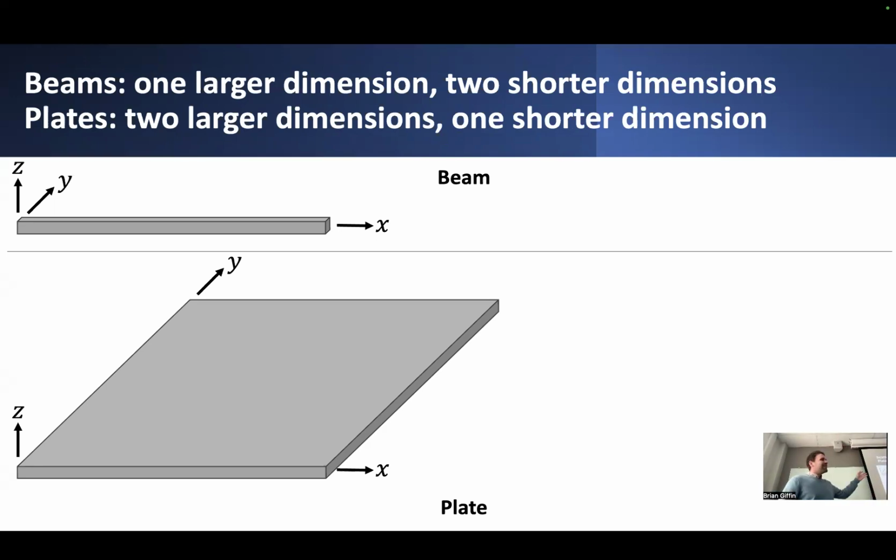So in some sense, beams and plates both involve this limiting process of looking at what happens to the elasticity solutions that we might derive for some general structure. What happens as we shrink these transverse dimensions to be smaller and smaller, increasing the slenderness of the beam, or basically shrinking this thickness dimension of the plate down to zero.